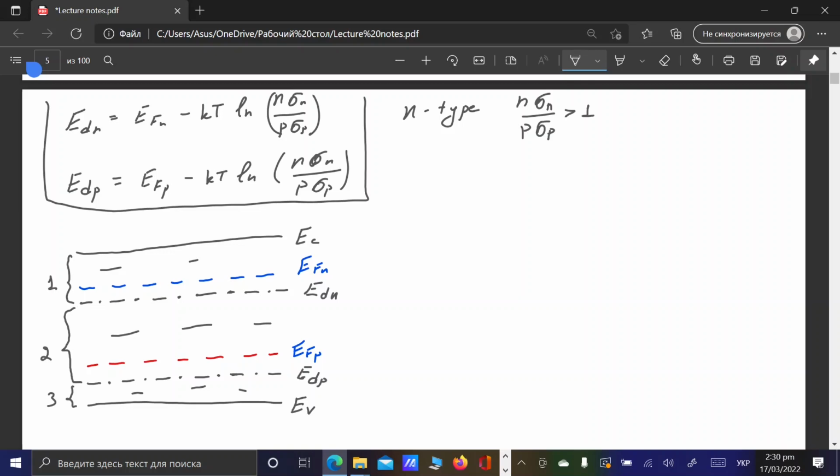Sure. So with this we finish the recombination part. We will come back a little bit to recombination when we have surface effects, because there will also be trap-assisted recombination at the surface. However, we already covered the most essential topics related to recombination: bimolecular, radiative bimolecular, trap-assisted recombination via deep energy levels.